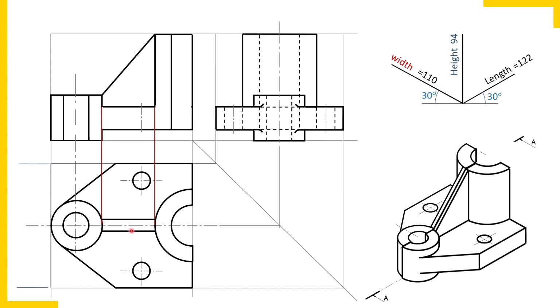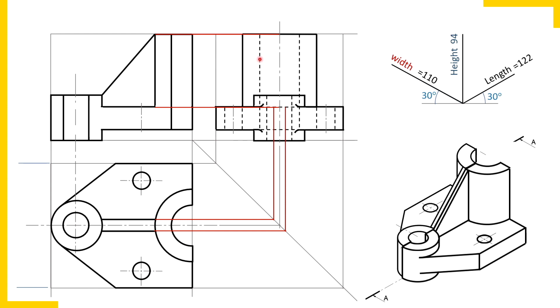Now the end projectors, and this is very important, where many students make mistakes. The extreme top of the trapezoidal plate to the extreme bottom of the trapezoidal plate is the height. So here I have projected the width of 10 millimeter, and here I have projected the height. Height is vertical in the side view, width is horizontal in the side view.